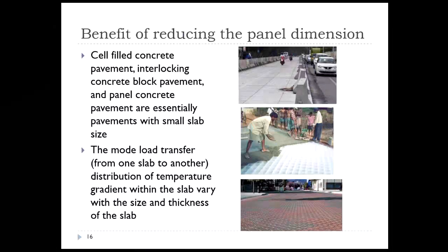Now the mode of load transfer, the load transfer distribution from one slab to another, and the distribution of temperature gradient within the slab may vary with the size and the thickness of the slab that we are considering.